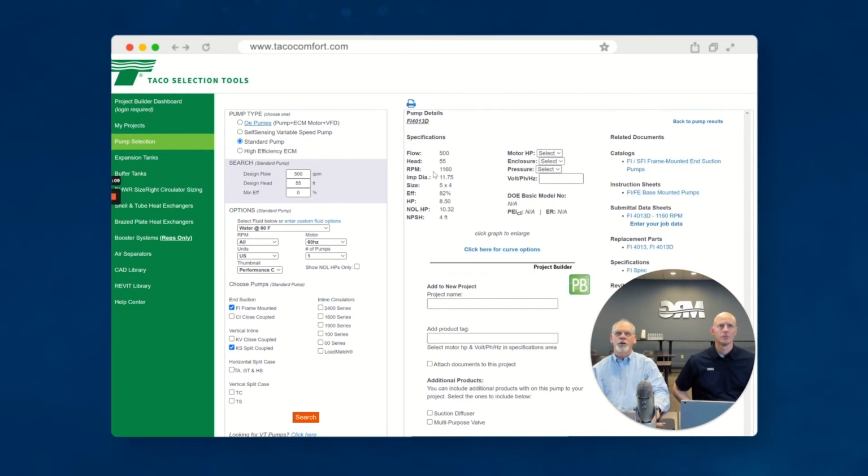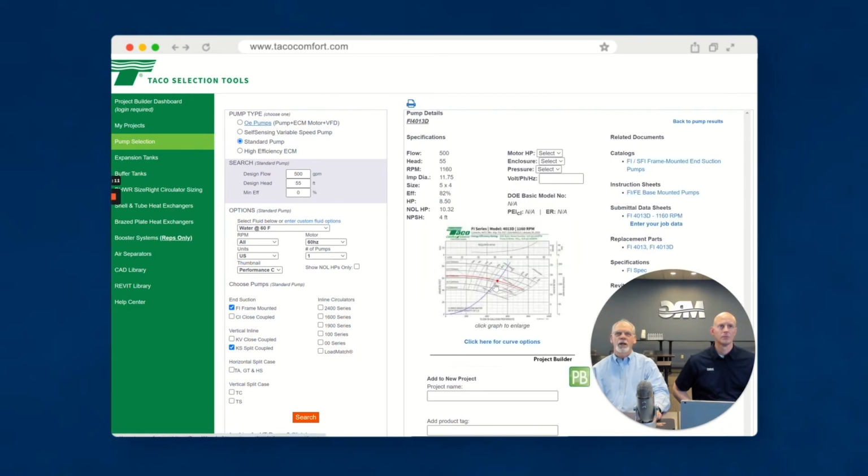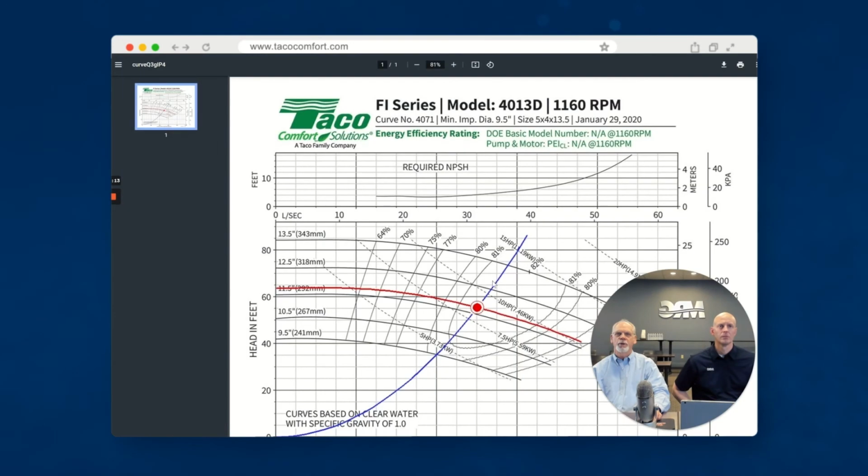On this one right here, if we look at this curve one more time, you get a lot of information off of looking at these curves. When we see from this point here all the way over to this point here, we're in the same efficiency. All right, so we got a good range of efficiency in there, and it's in this top portion. It says 81, but 82 is the best you can do. Yeah. So we're in a good place in this pump, and it's going to work well for you.